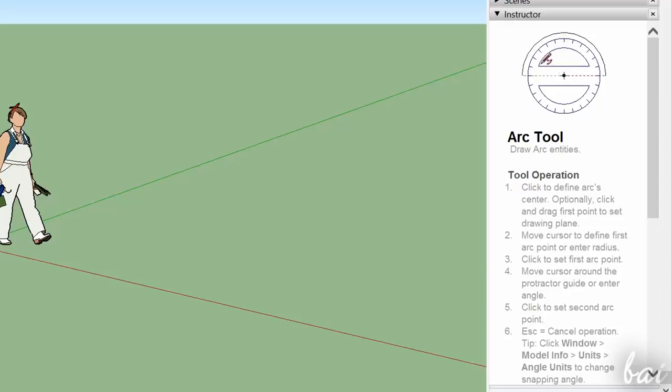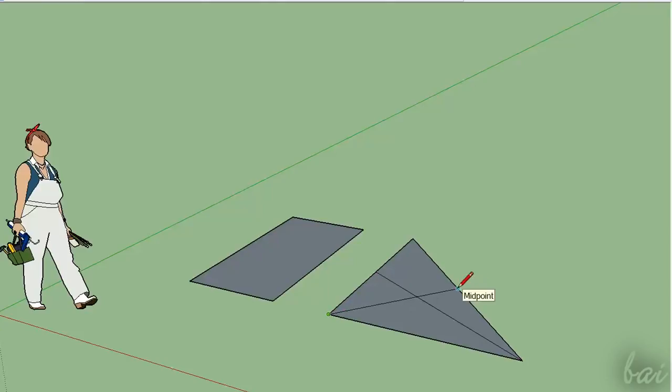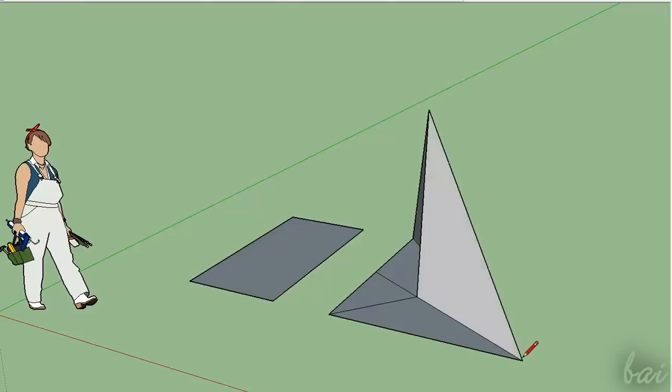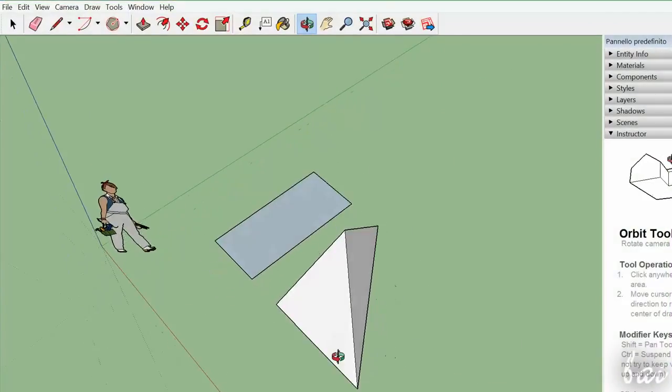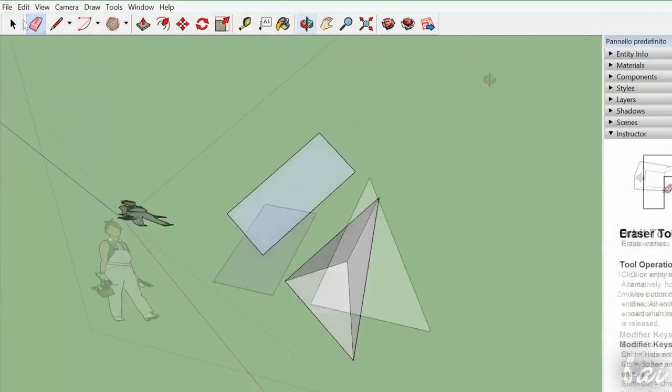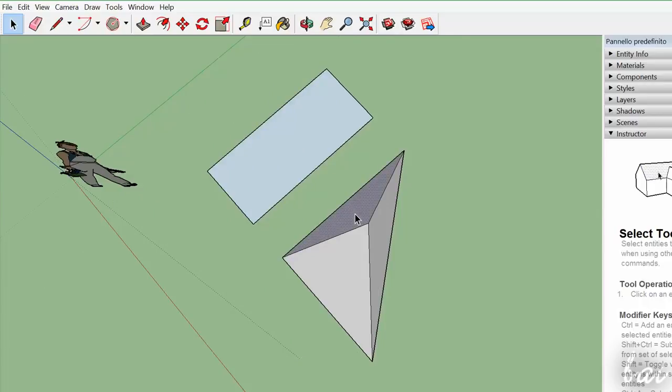Let's now see how to draw and create 3D objects. For example, you can build 3D objects completely manually. The filling that is created when you close paths is the same one used for the faces of a 3D object. So, to create a 3D object, it is sufficient to create all the necessary faces to complete it. Just mind that, once finished, all faces created will remain independent, and this can be hard to manage in the